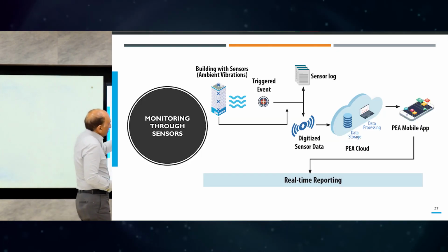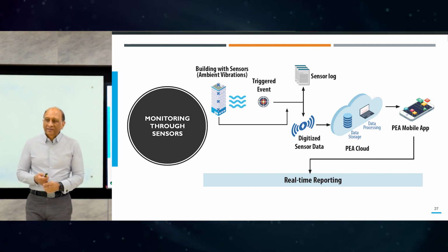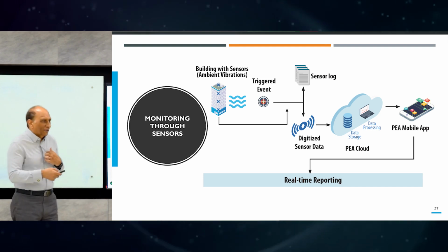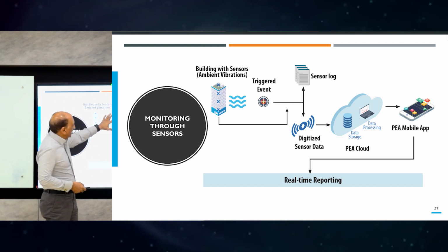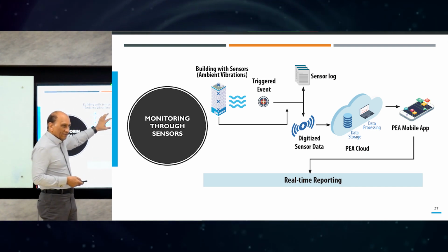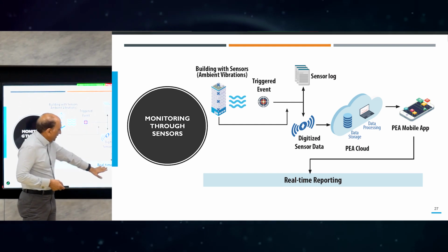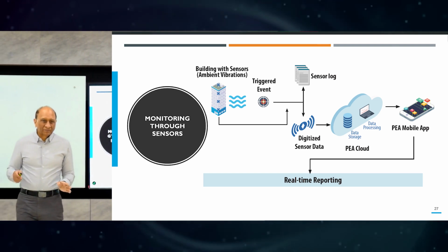This is, for example, just to give you an idea how structural health monitoring can work at a city level, like they implement in California and some places. We try to do it in the Philippines. So you have the sensors in the building, you measure the actual response after the earthquake, you get the results, you check the response, you have all the model, and finally you can do real-time reporting whether something happened or not.